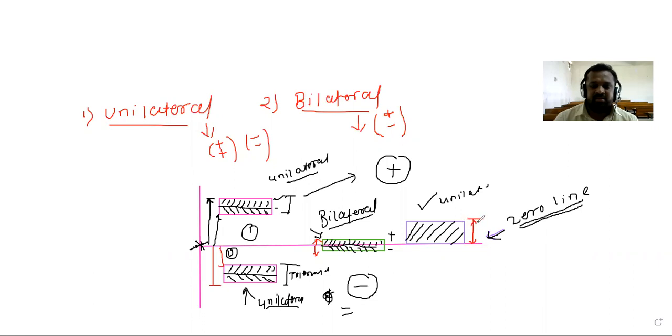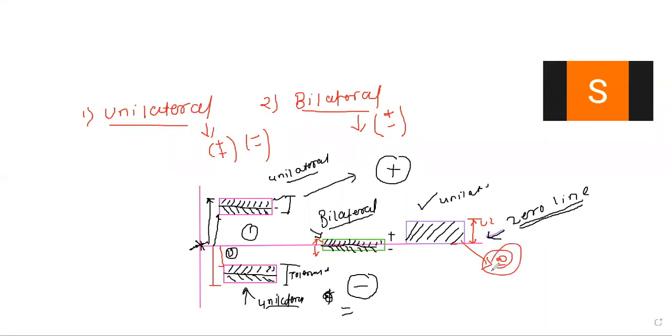Yes, it is the upper limit. And what is the lower limit for this tolerance zone? Yes, what is the lower limit? What will be the lower limit for basic size? Means it is the zero limit. Means on the lower side they have not shown the lower limit. Okay, it will be the zero. This is called the graphical representation of your unilateral as well as bilateral tolerances. So, understood how to show unilateral and bilateral tolerance graphically.